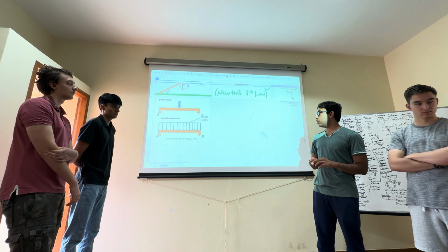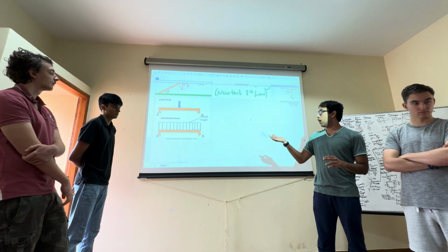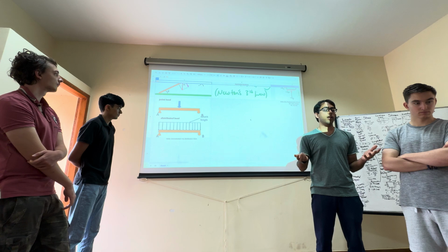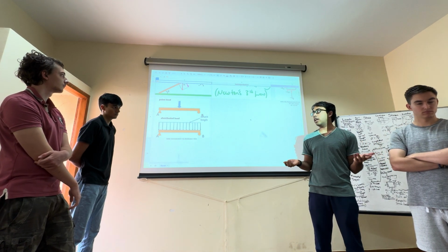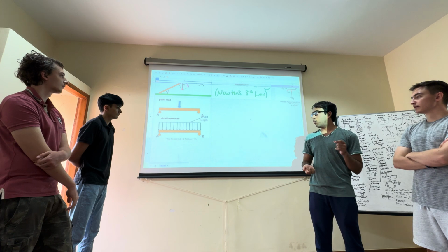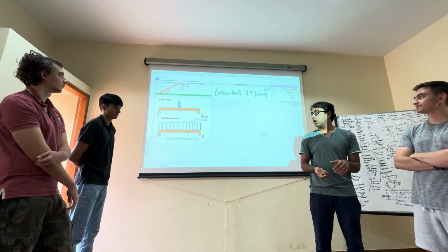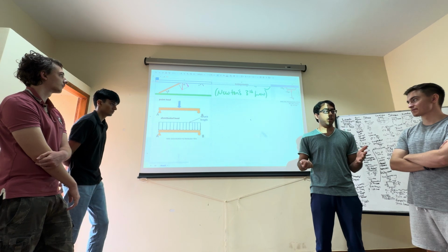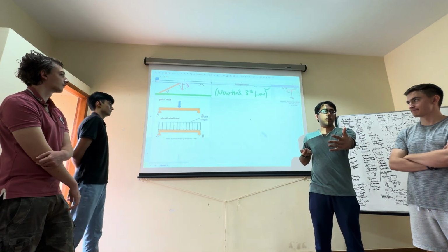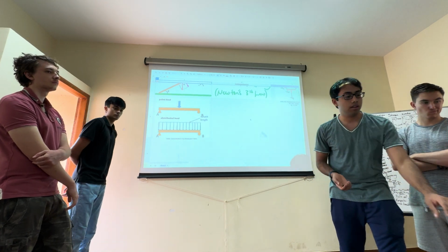One more thing with units that I wanted to talk about is that the units for loading conditions aren't necessarily constant. Last time we had it as purely newtons, but we know that's not the case. With our example here, a point load or concentrated load will have units of newtons, whereas if it's distributed, it's going to be newtons over meters because it's distributed over the length of whatever beam it's being applied on.